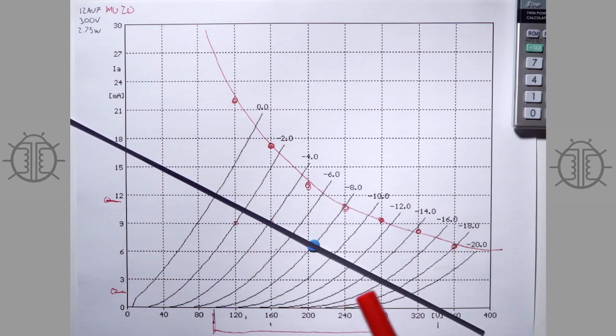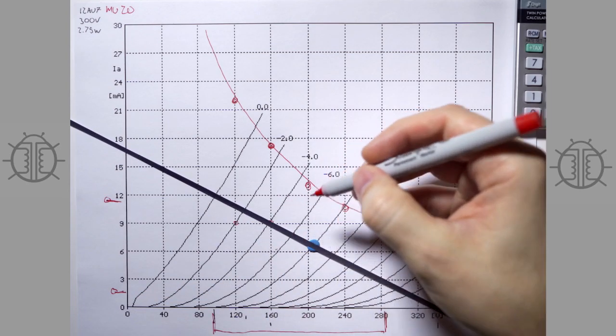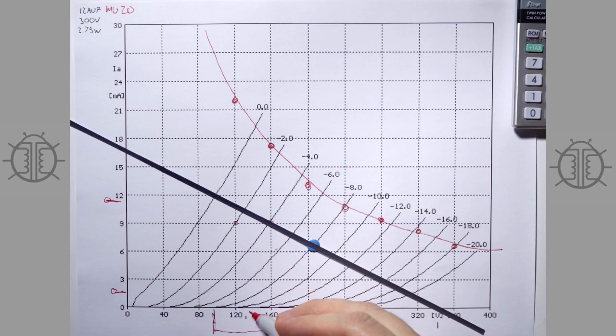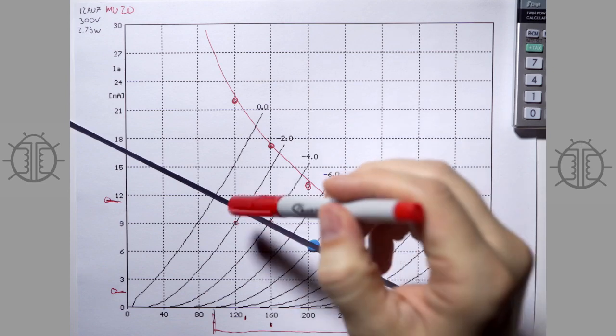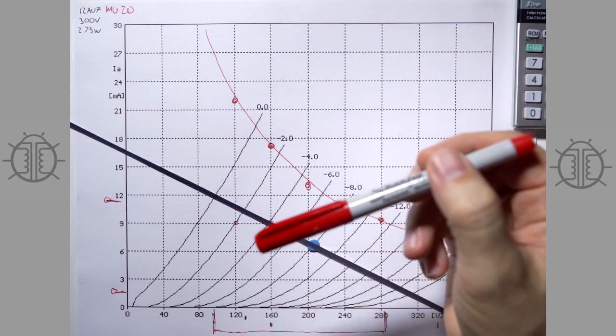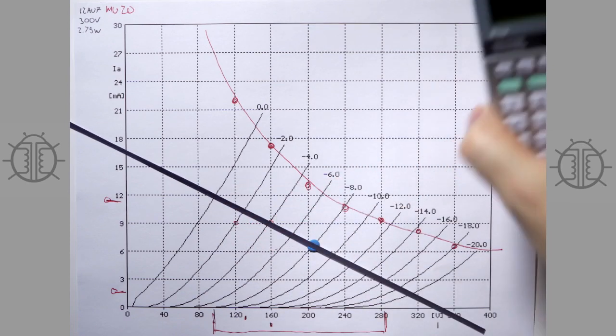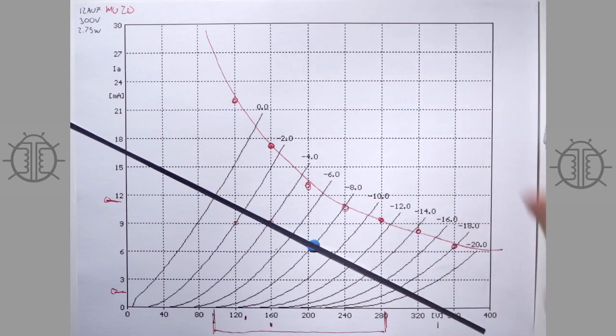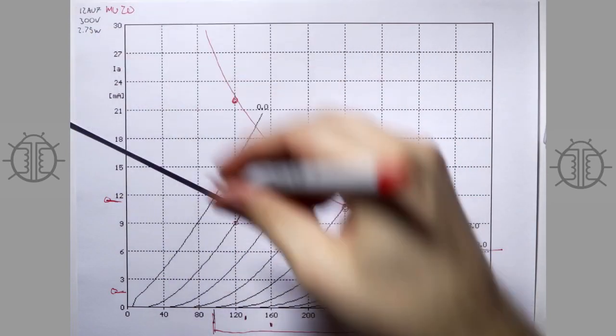Now you can see as you load the tube back to our operating point here, the gain decreases. So now we can look and see the difference between 2 volts here is going to end up being something like this. So 2 volts will be now, I don't know, it's less, let's take 10 off of that. Maybe it's 30 now, and so it'll be 15. So now our gain's down to 15 with this load line.